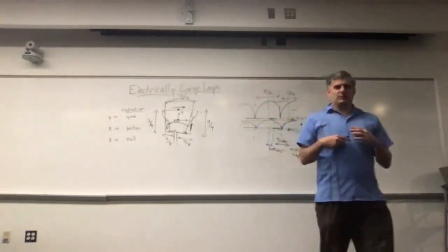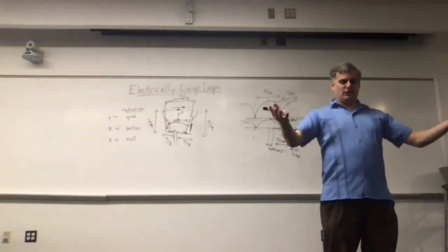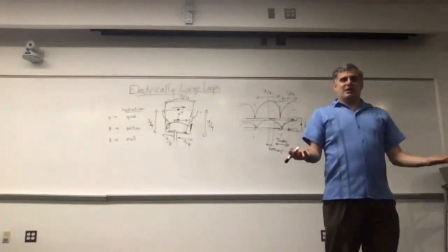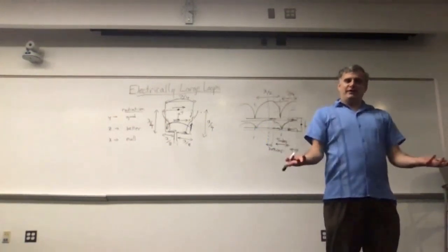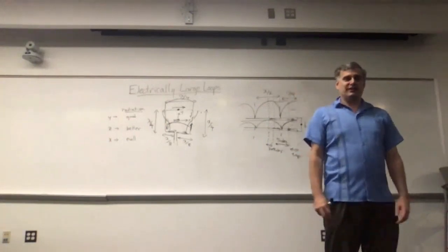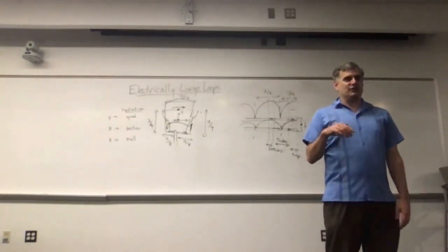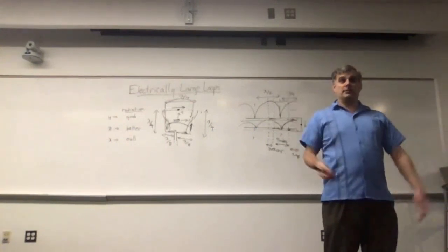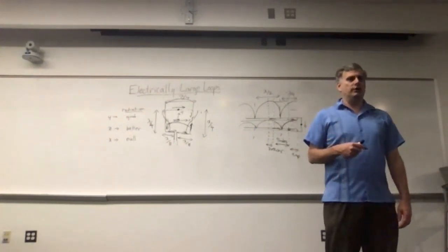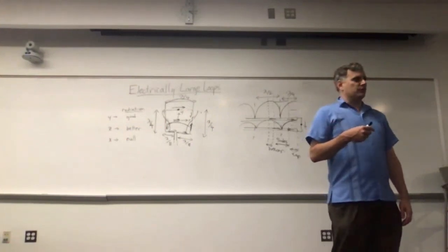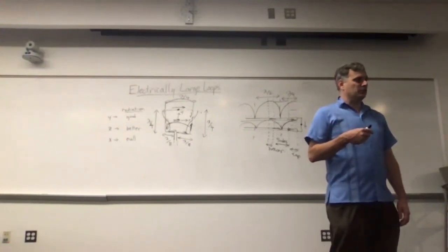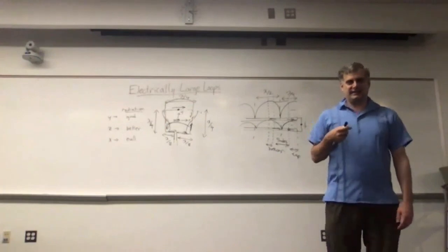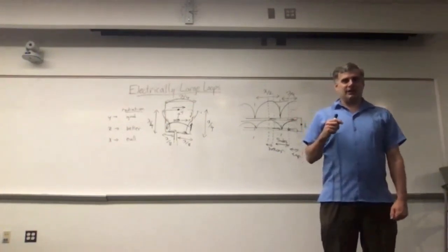There's also a mechanical stability issue you get with these planar antennas. You make them out of wire, but they're kind of saggy, right? They don't behave the way you think unless you have something that is translucent to RF to prop it up. Piece of cardboard, piece of wood, poster board from your store. That stuff is basically invisible to RF if you ever need to build an antenna and mechanically stabilize it.